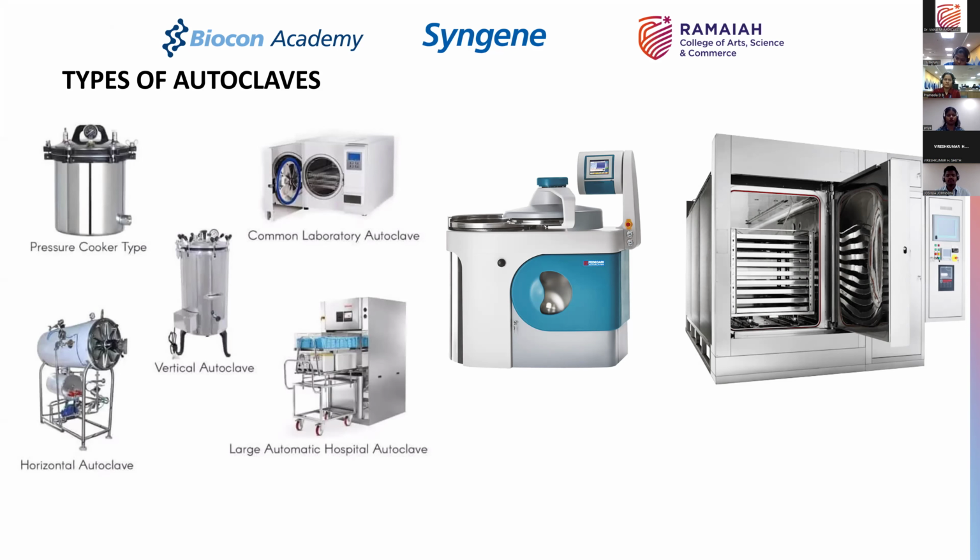So you would ask me, why would somebody choose the most expensive type? It is again dependent on what application you are going with. If you're going with a laboratory application, obviously you're not going to use a large autoclave of negative pressure. You could use a vertical autoclave in its place. You could use a horizontal autoclave and combine it with vacuum if you wanted, even in the laboratories. But it is generally not required, because the cycles or the load is very, very small, and you are trying to sterilize it.